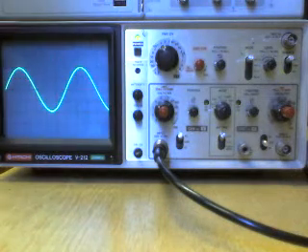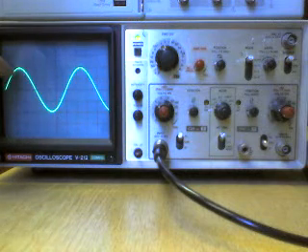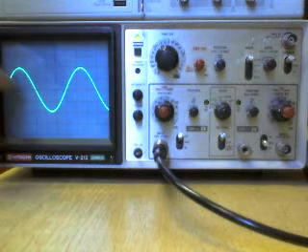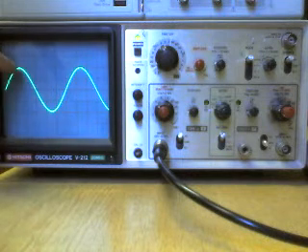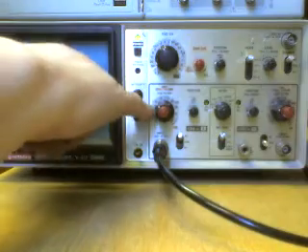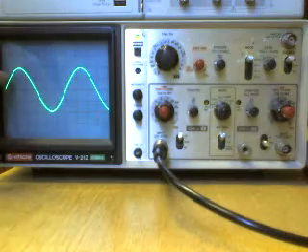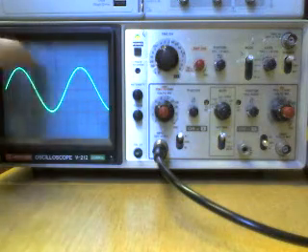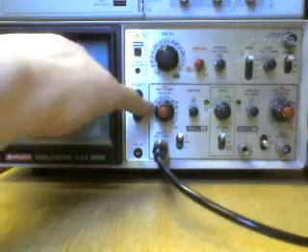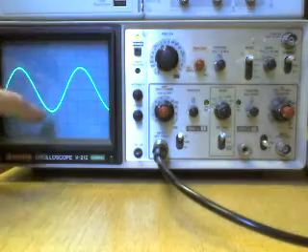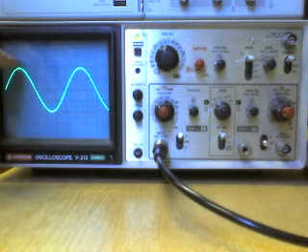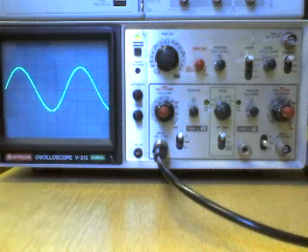Voltages, same thing. So what do we have? We've got, not 2 volts, sorry, we've got 2 divisions. From the centre to the top peak is the amplitude, and it's 0.5 volts per division, so that's 1 volt amplitude. The same thing negatively: 2 divisions multiplied by 0.5 is 1 volt going negative. 1 volt positive, 1 volt negative, we've got a peak to peak of 2 volts.